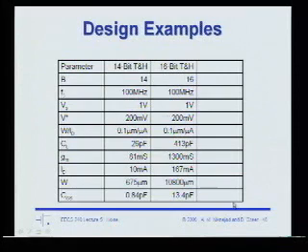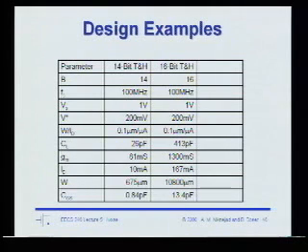Okay? And also it costs us a lot in area too. I have to make my transistors larger, I have to make my load capacitance larger, so going to higher resolutions has a power penalty and an area penalty. Okay? Questions or comments about this example?